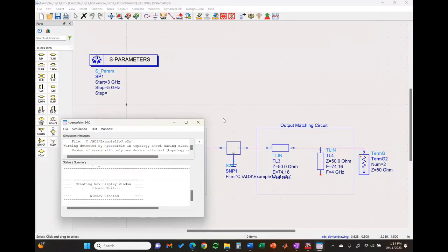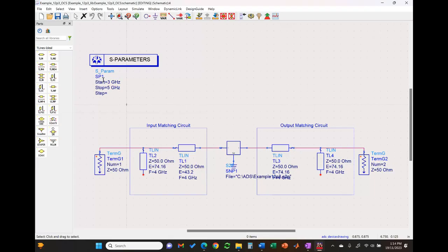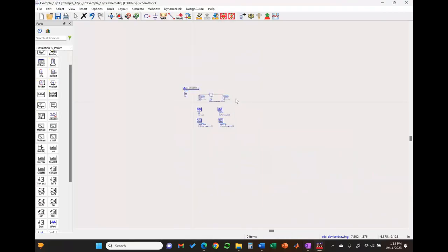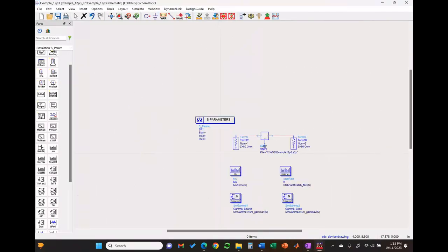Professor, I just had a thought, whether it's possible or not. Can we have two different kinds of matching networks? One could be using stubs at the input and maybe an L network at the output. Yes, that's definitely possible. It's a matching network at the end of the day. It doesn't matter how you build it, right? Yeah, you can mix if you want. That's fine, and sometimes you might actually mix them to maximize the bandwidth in some applications.